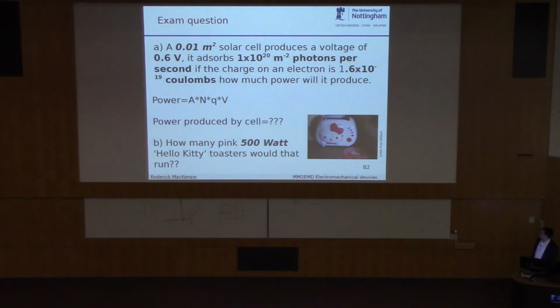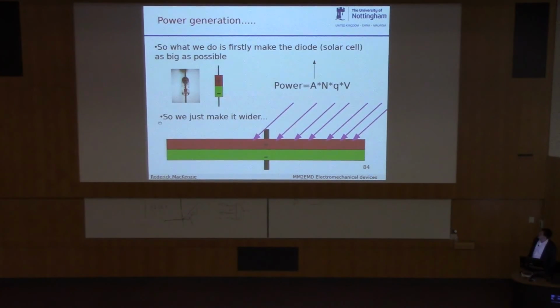And then we can do some calculations, and I've got you to do some calculations. The only difference between a normal diode, something you use for power electronics, which looks like that one up on the left, and a solar cell, is that some clever manufacturer has taken the diode and spread it out to be a nice big, wide panel so it can absorb lots of photons. What affects how much current or power you get out of a solar cell is the built-in voltage between one contact and the other, and the number of photons it absorbs. You can increase the number of photons it absorbs by increasing the area and make it better. So that's the sketched example of how solar cells work in a very quick cartoon fashion.